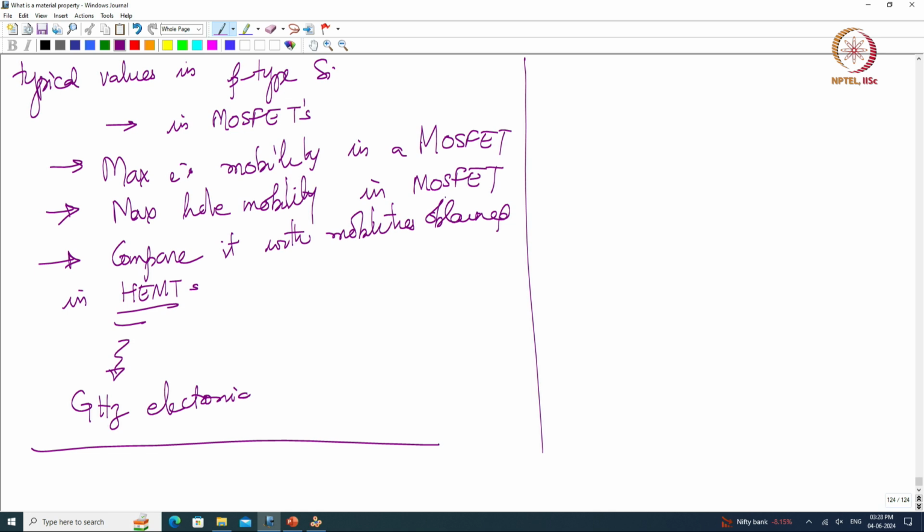These are the keywords that you can search and find out for yourself. The key point here is that fundamentally, what I am doing is creating a polarization discontinuity in a couple of Wurtzite structures, and by creating this polarization discontinuity, I am bending bands in such a way that the only way this polarization discontinuity can be charge compensated is by adding some extra electrons. And these are free electrons.